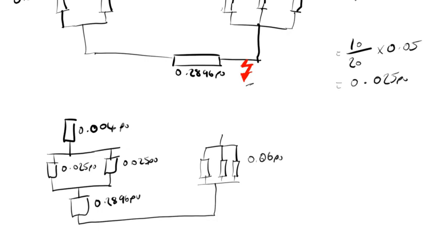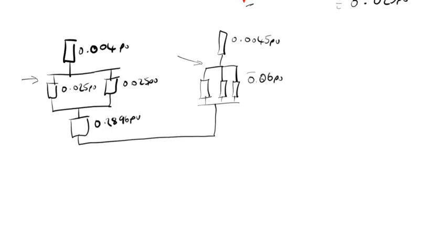So then we can calculate the parallel impedances per unit values of these just by using simple parallel and series techniques. So basically if we reduce this down, say for instance this one here, you would have 1 over 1 over 0.025 plus 1 over 0.025. It's kind of similar to what we do in Ohm's law.